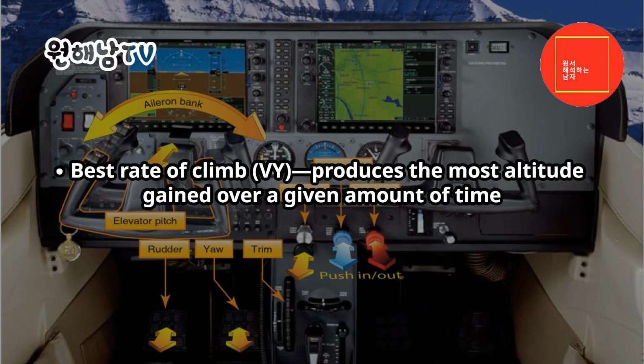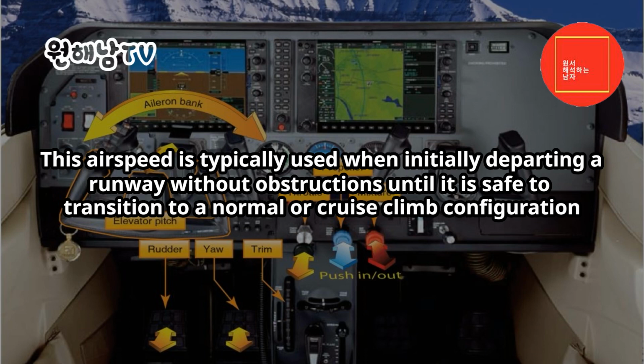Best rate of climb, VY, produces the most altitude gained over a given amount of time. This airspeed is typically used when initially departing a runway without obstructions, until it is safe to transition to a normal or cruise climb configuration.